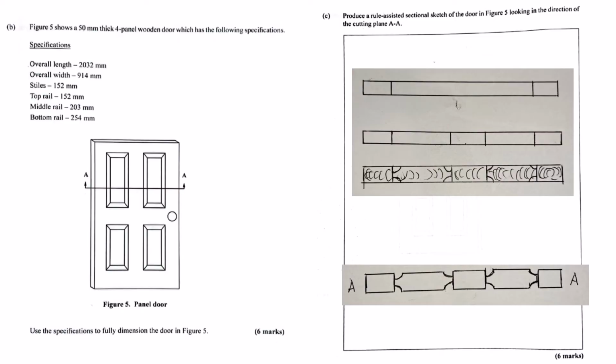Okay. Subtract that 609 from the total door height of 2032. That leaves us with 1,423 millimeters. And that's the space for the two panels, top and bottom. That's the total vertical space the two panels have to fit into, one above the other. So again, divide that 1,423 by 2. Each panel ends up being about 711.5 millimeters tall. So again, subtracting all the frame pieces leaves the space for the panels. And these calculations have to be pretty spot on, right? Because if the panels are off even a little bit. Oh, absolutely. Precision is everything here. If those panel measurements are wrong, you'll have gaps or they just won't physically fit. These calculations make sure everything slots together nicely.